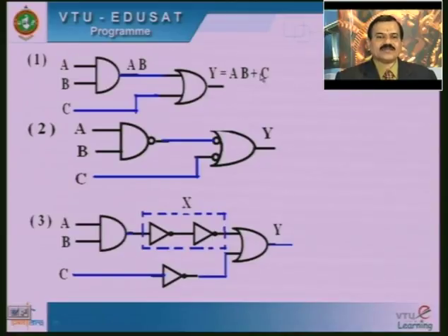So what the first point says is, if your intention is to create this logic realization with only using the NAND, then in this particular circuit which is created with the basic gates, wherever the AND gate is there, that AND gate must be added by a bubble at its output, and the OR gates are added by the bubbles at the input.